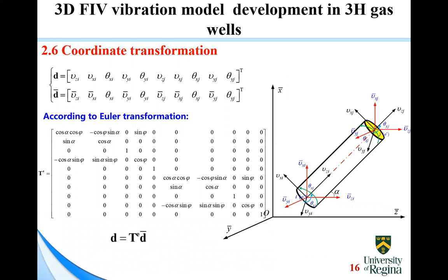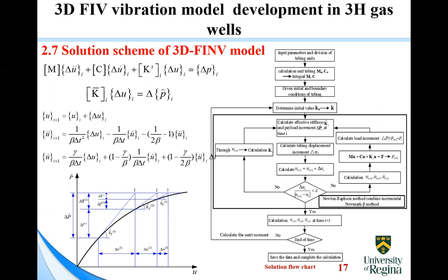We also know the finite element method is used, but in the HPHT gas well, there will also be directional wells or horizontal wells. So we should do a coordinate transformation. With the coordinate angle transformation, we can get the coordinate transformations expressed by this equation.